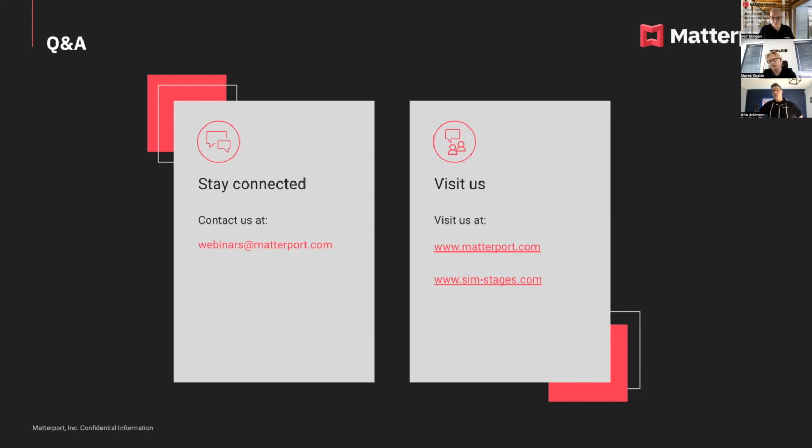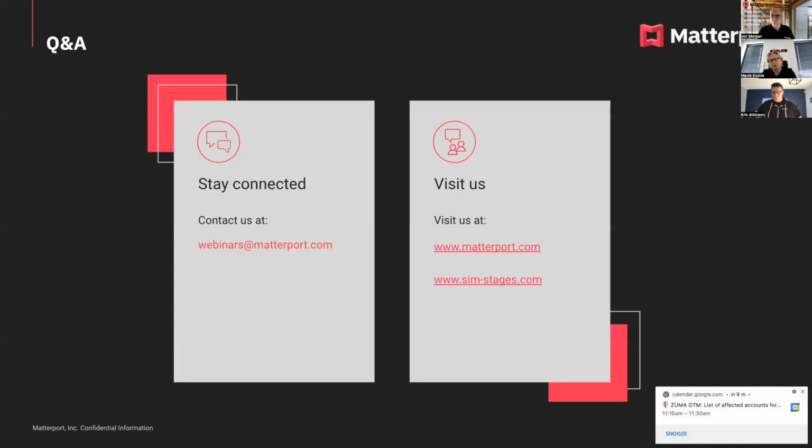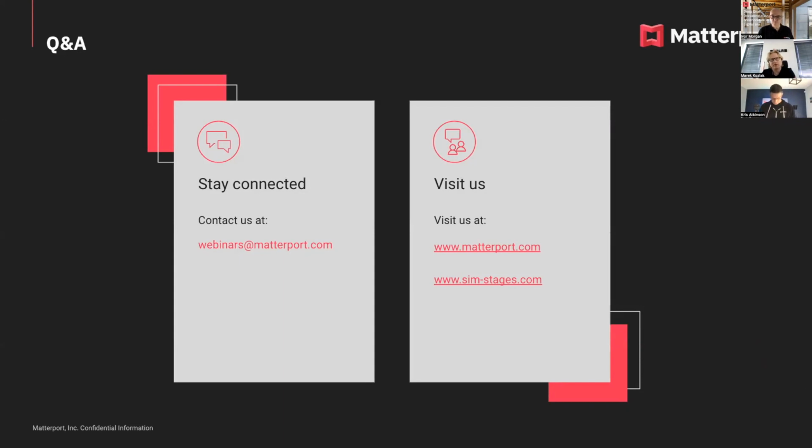On top of that, we are giving FBX, which is a very common format for 3D graphics, which can be from your interior designer. But I guess that you are mostly interested in the BIM data format. So IFC is the standard that we are supporting inside of the Stages desktop, and blueprints in the PDF format. We are working on DWG, so it's going to be launched in the next couple of weeks. But today, IFC data is what you are exporting from Revit and Archicad, and we are able to read it natively inside of the Stages. Brilliant, thank you very much, Marek.